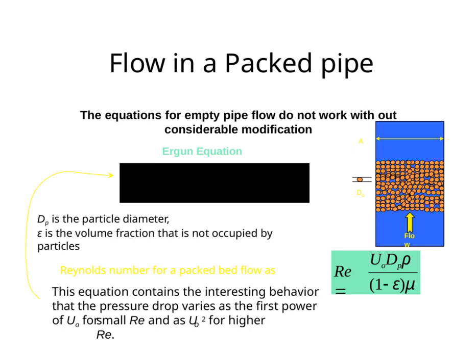It shows how pressure drop relates to flow velocity, especially at low and high Reynolds numbers. Here, the Reynolds number depends on particle size, fluid properties, and how much space the particles leave open. This gives us a clearer picture of flow in these more complex, packed systems.